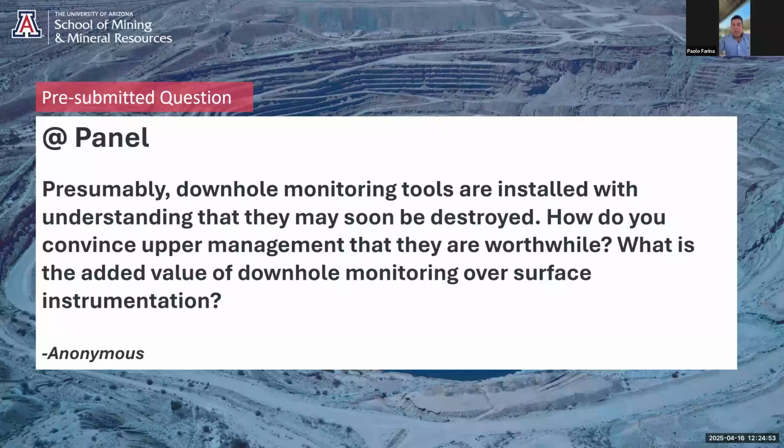Could be a TDR, could be a manual inclinometer, could be a shape array, whatever. But this will confirm and tell you the depth and then what is the mechanism. This is something you need to understand, first of all, to understand the potential impact of this moving area on operation, because the volume does allow you to estimate the runout.